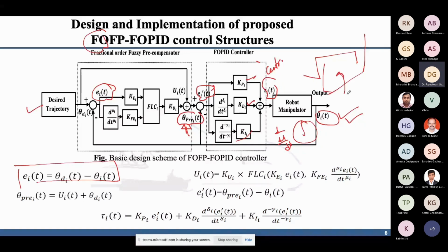Here we are considering that the motor generates the torque as per the control action. If we neglect the motor, then torque is equal to the control action, so that's why we have neglected it. It doesn't matter when we are doing the simulation, but if you are going for a hardware application, then it is required. Otherwise the motor is not going to move your hand, your manipulator, right? Okay, so this is your output at last, right?